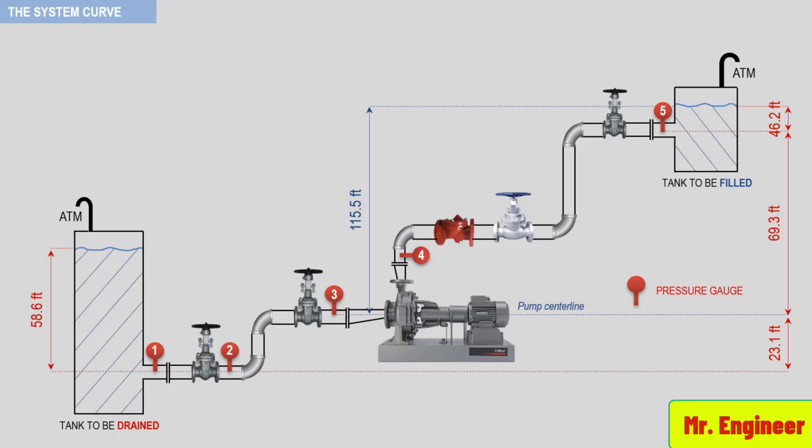With the system and pump turned off, we would open the vent valves on both the suction and discharge tanks. This assures that both sides of the system are atmospheric and then cancel the pressure head. The discharge tank and all piping should be full with water for the test, or if required with the pumped liquid. Remember that gauge readings will be adjusted by the specific gravity.